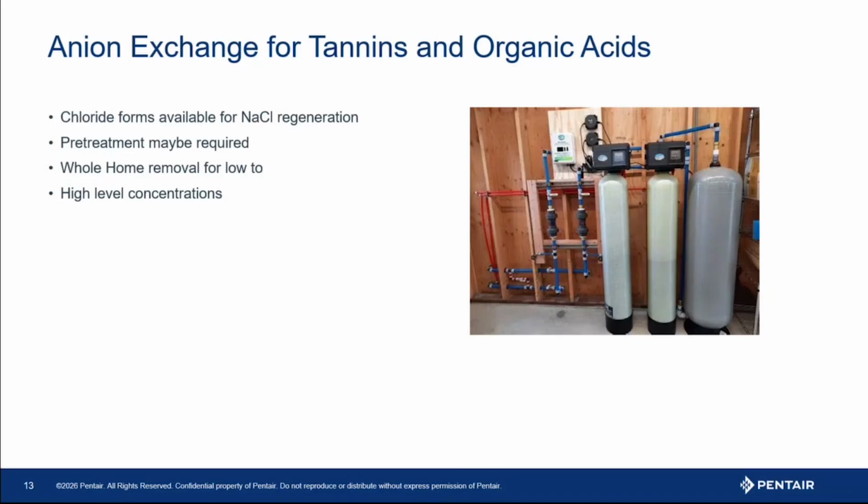This is the best solution for higher levels of tannins in the water. But it's also very, very good for low levels of tannins in the water as well. But those low levels of tannins can be a little more cost effectively reduced with activated carbon. It all depends on your water quality to start with.